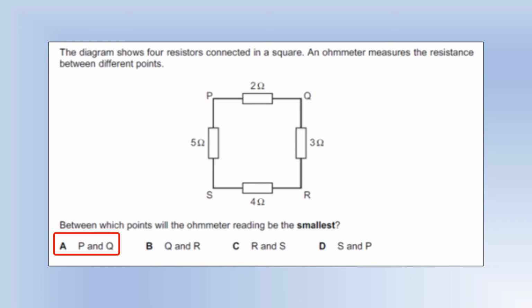So I would put it between P and Q, because that gives us a total resistance that must be less than 2 ohms. If we pick any other way of connecting them, we're going to end up with a higher lower bound for it. And you can actually try this out and plug numbers in to test it out if you want to, but we're going to end up with Q when you plug the numbers in.